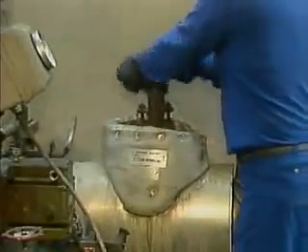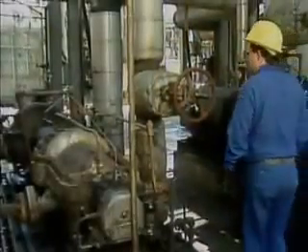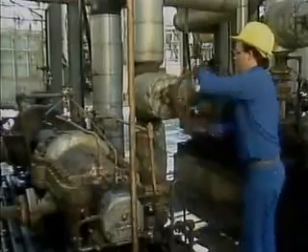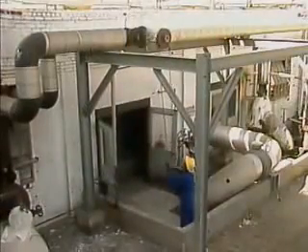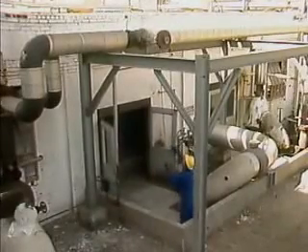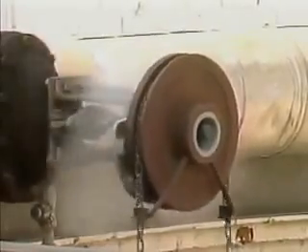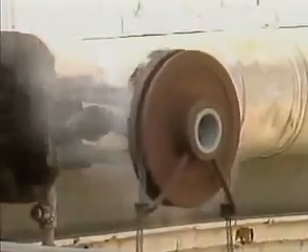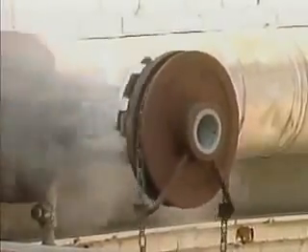Many valves can be opened or closed manually with a hand wheel. Ordinarily, the hand wheel is located so that the person operating the valve can apply the proper force to turn the wheel. In some situations, however, this isn't possible. Often, valves must be located in relatively inaccessible places. When this is the case, adapters may be attached to the hand wheels so workers can operate the valves. A common example of such an adapter is a chain that runs through a pulley.